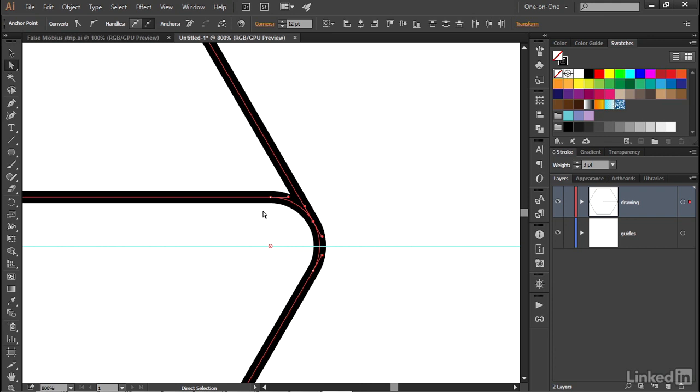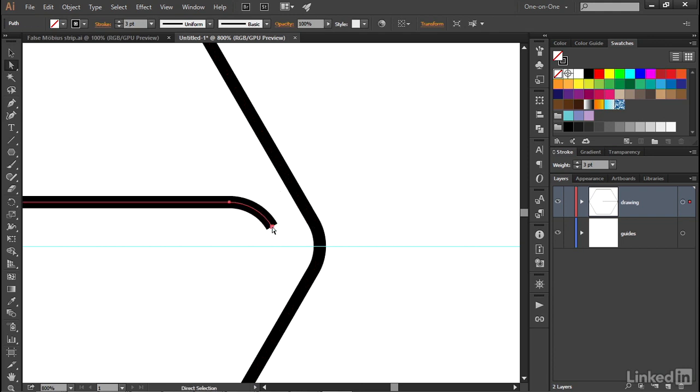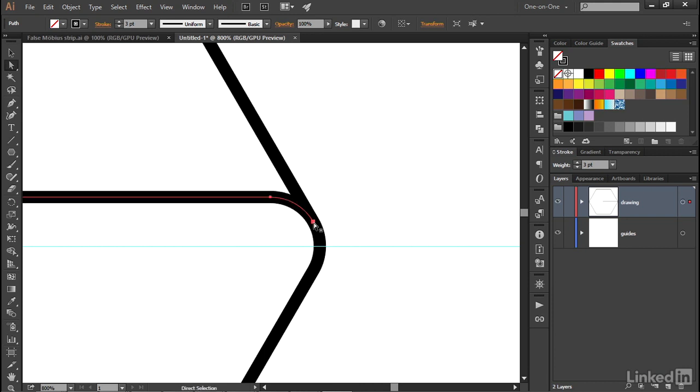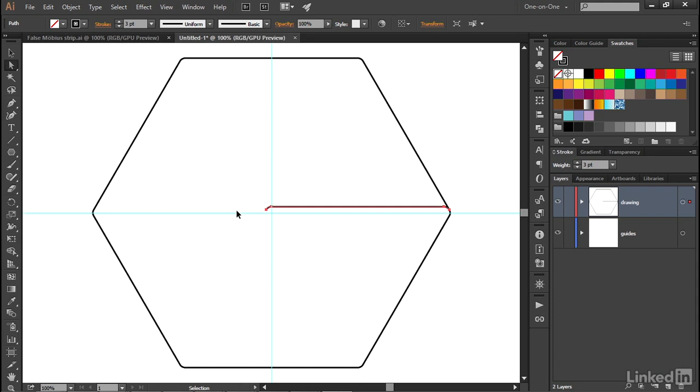And if you want to confirm that, then you can Alt-click or Option-click on this open path outline to select the entire thing. And then you can drag it away, like so, and make sure to drag it by its endpoint and drag it until it snaps into alignment with a stationary anchor point. And you'll know that you have a snap because your cursor will change to a white arrowhead, at which point go ahead and release.